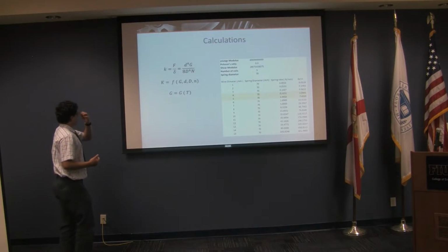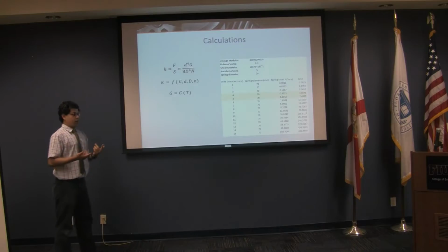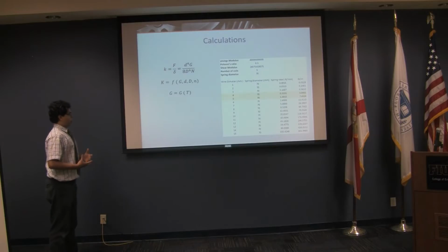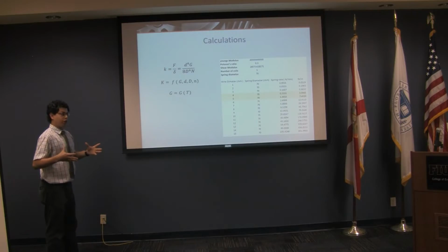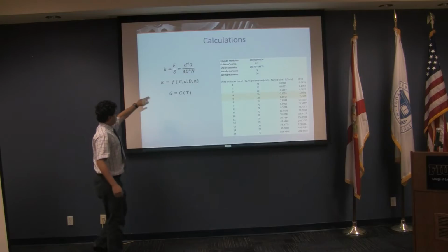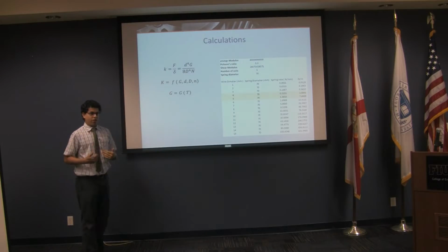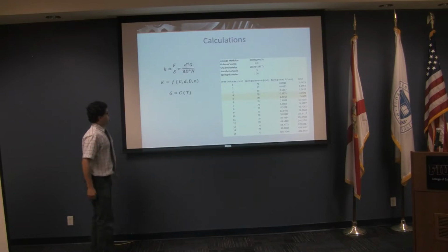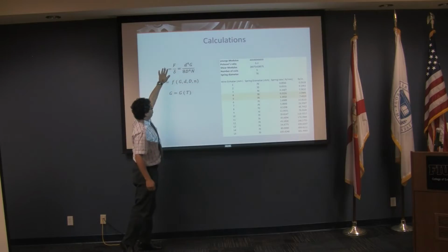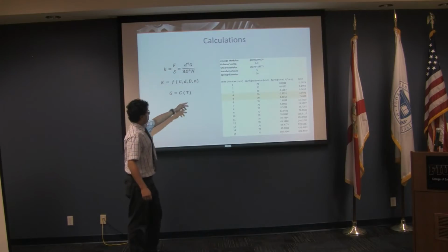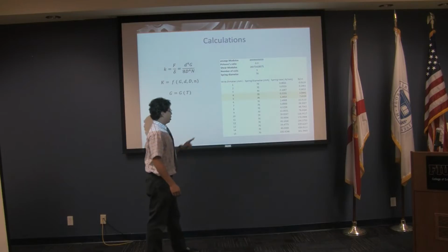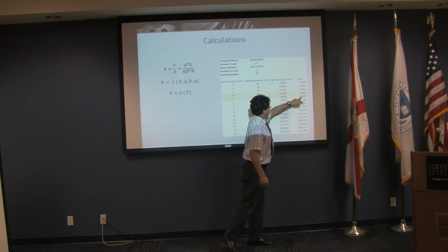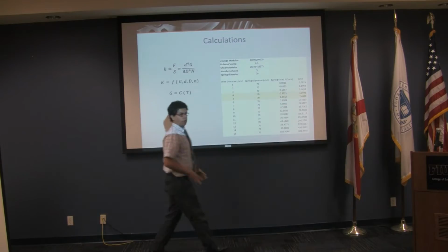We found these formulas which relate the K factor of the spring in terms of the shear stress, the diameter of the wire, and also the diameter of the spring. So doing that and taking G as a function of temperature, because the material changes stiffness, the Young's modulus changes as you change the temperature. So we put this function inside this other function, and then we start to tabulate, as we see, to find the optimal wire diameter that will give us the K factor as we want for a scale model.